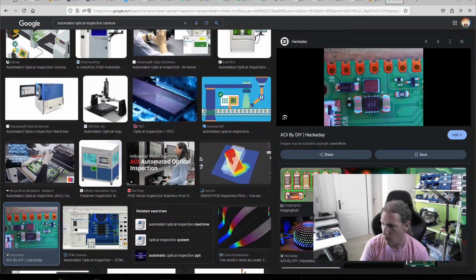So some way of defining a 3D representation of the machine at a simple level. It doesn't obviously need to be a complete proper 3D model of it, though people could do that if they wanted to, technically. So defining where the bed is, for instance, defining where your feeders are, defining the extents of where a head can move to with a nozzle retracted, knowing how far a nozzle can retract or is retracted.